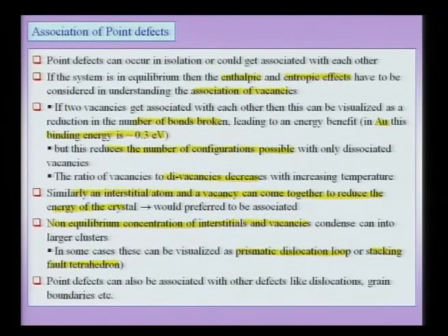The important point to note is that not only can point defects get associated with themselves, but they can also get associated with other kinds of defects like dislocations and grain boundaries, and this again would lead to the lowering of the energy of the system in many cases.